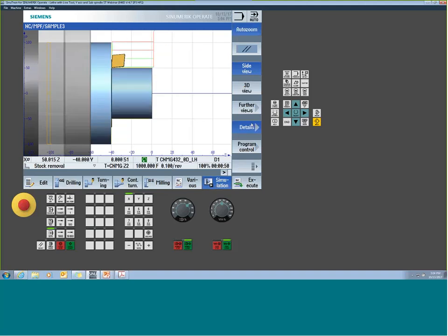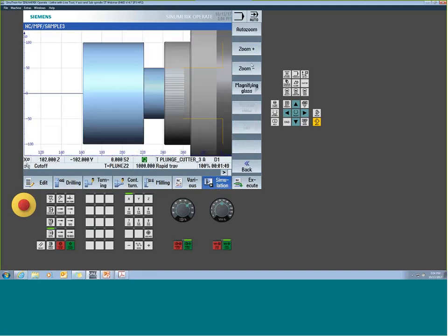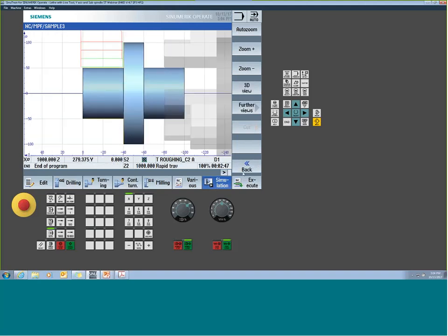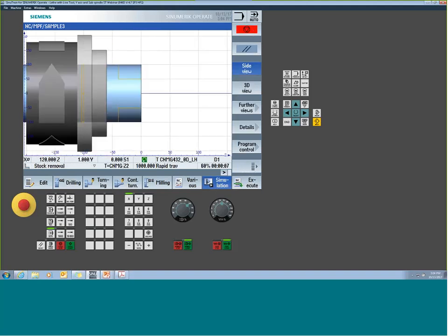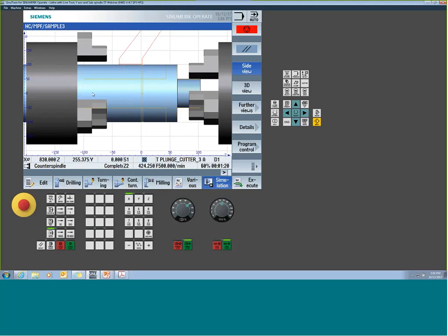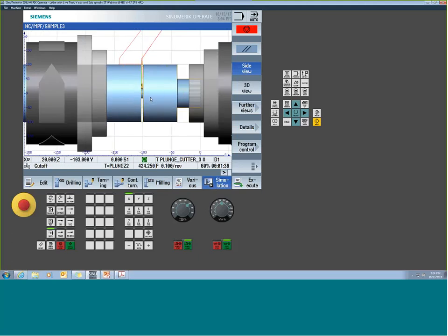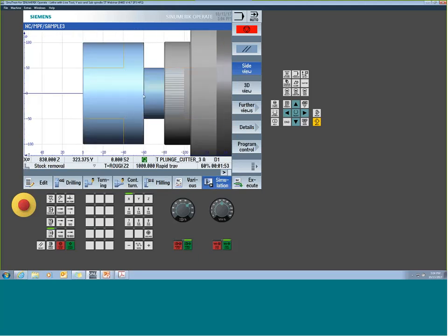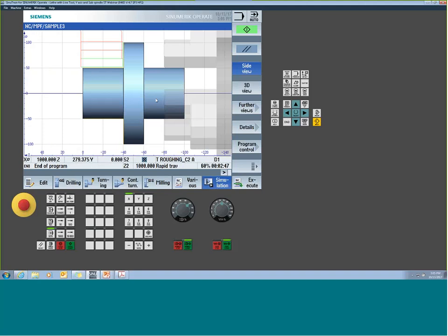All right, so I'm going to slow things down a little bit, and we're going to rerun this. So there's your backside. Okay, I want to just slow things down a bit, and we're going to talk about this. You see I'm sticking out my 60 mil. My sub spindle comes over, grabs, that's my draw. So the big question usually is how does it know how much it's going to draw? How far back it's going to go? I wasn't asked that question anywhere.